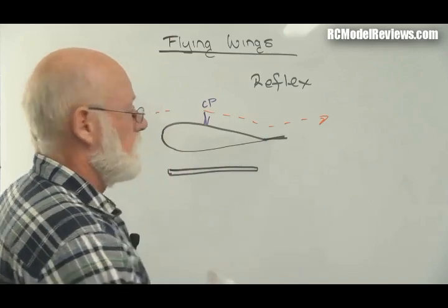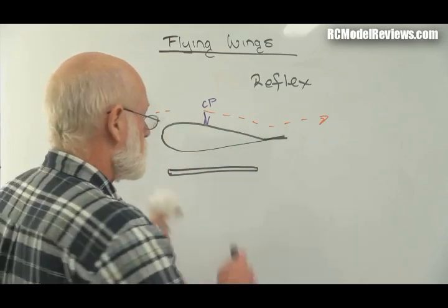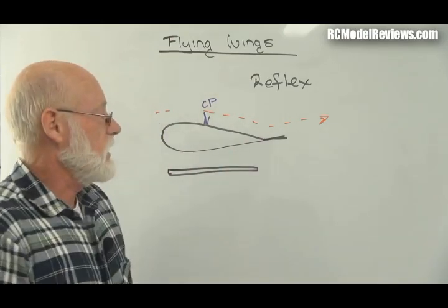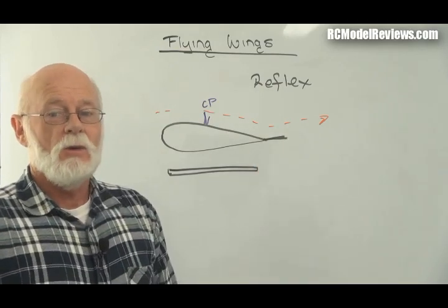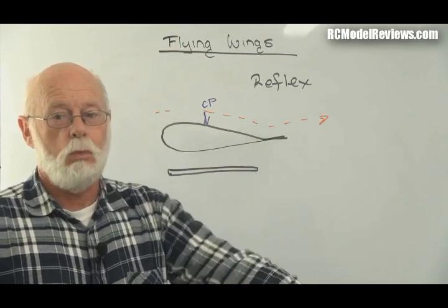There you go. So most of my wings, as I say, have symmetrical airfoils. But that's the lift side of things. That's why we have reflex. That's why reflex is important. That's why no flying wing will fly without reflex. It'll just lawn dart every time.